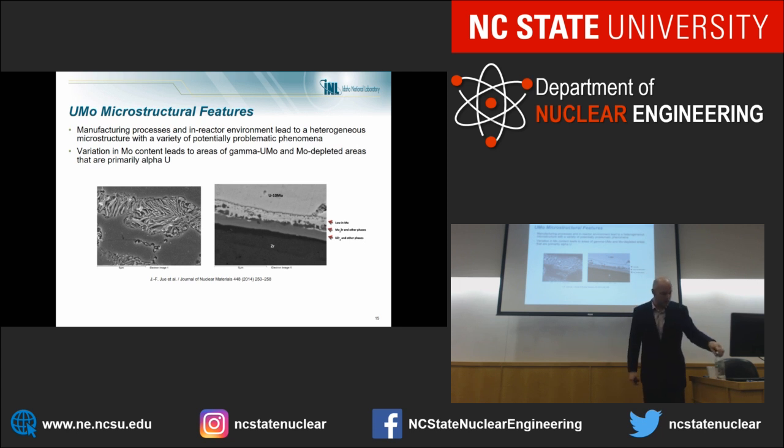So some other features that we have in U-Mo fuels. Whenever we make this fuel, it's not going to be pure BCC U. We're going to have decomposed regions, and that's what I'm showing here, this kind of folded structure. We have one grain that is BCC U-Mo, another grain that is BCC U-Mo, and then typically along a grain boundary, we have the structure decomposed into alpha U and this U2Mo structure. So we have these folds where it's no longer the BCC phase.